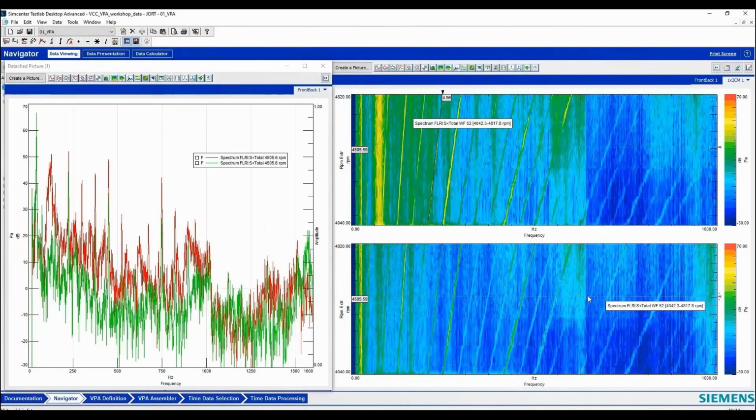And then you will get a result like you can see here in the image, where you can say, for example, for the driver's ear, what is the sound that is produced by this pump if I would integrate it in this vehicle on this position. Here we compare position 2 and 3. You see, for example, immediately from this picture that position 2 has much higher noise levels than position 3. So in function of RPM, I see here the different spectra, and I can check them here, and I see already that the frequency is at a much higher level. It gives you a very easy way to evaluate these different positions and make decisions using these predictions.